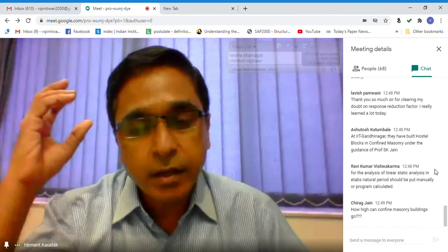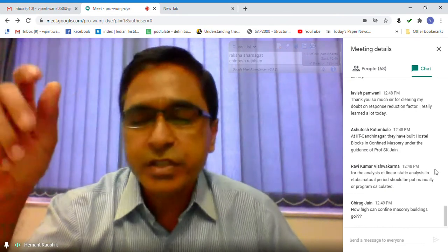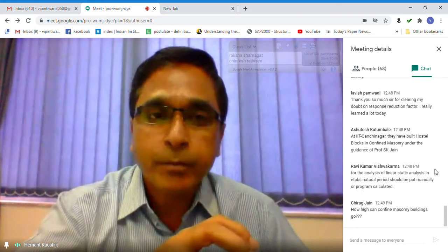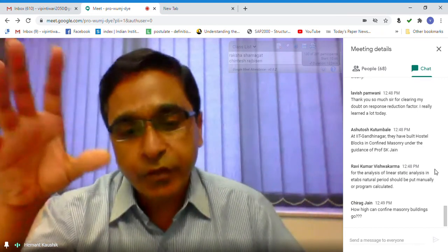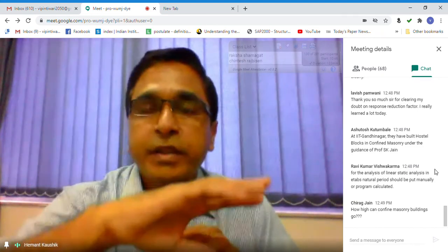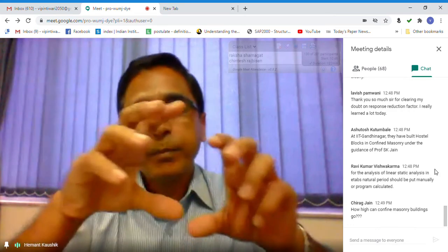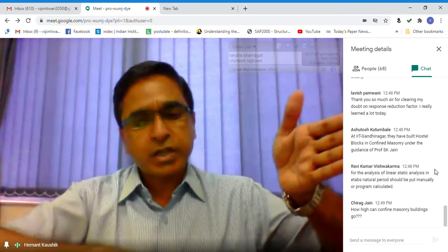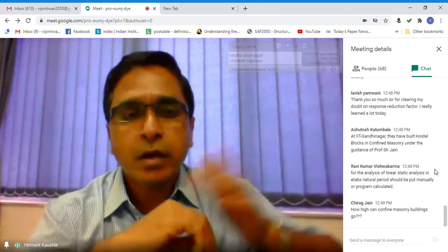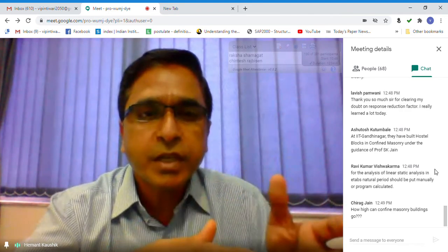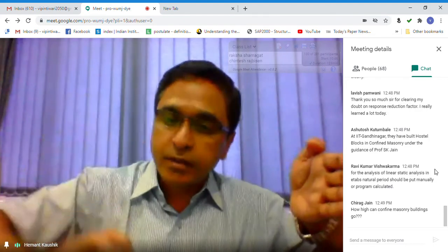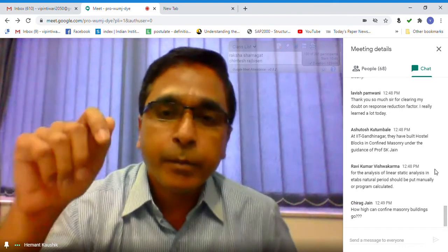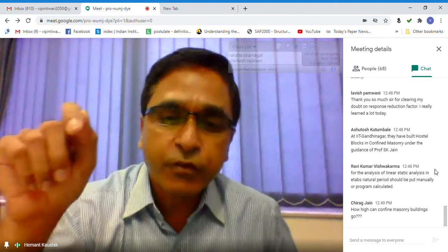Only some members, which are responding to this vertical shaking, are vulnerable, right? So you have to identify those, and when you do the analysis, you apply the vertical force and see how much the design force is there. For example, a large overhang. If you apply horizontal shaking, it may not be that influential in this case. But if you apply vertical shaking, then this member will vibrate more. So you have to identify those members and design them considering the design forces from a proper analysis.